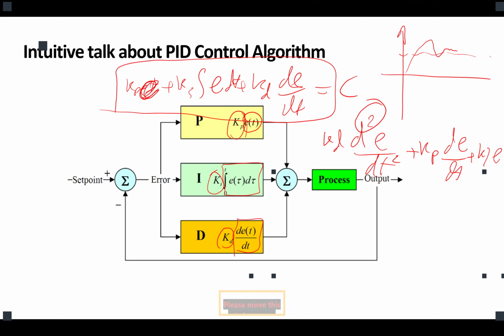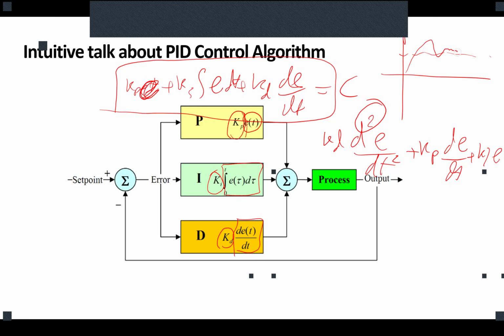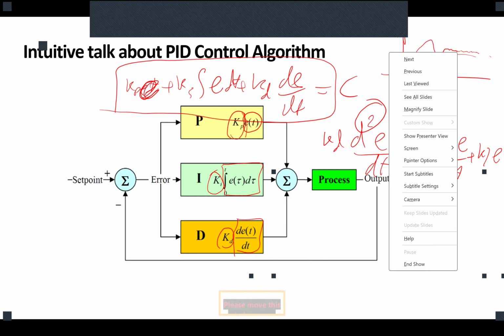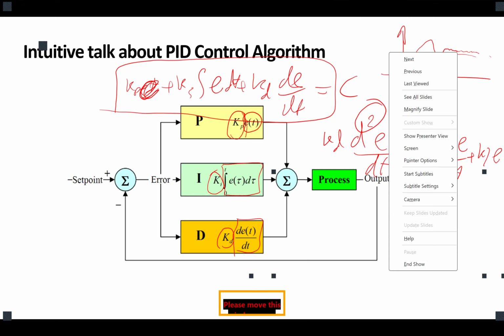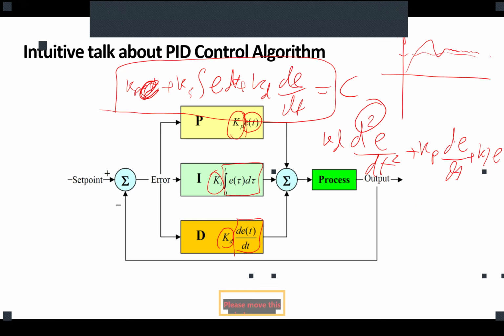So basically it means you can consider that it never gets to the set point, because it's like an exponential decay. It would approach the set point and never reach it, because as much as you get closer, the error never gets to zero, since a proportion of the error is added to the control signal. Are we good? So we are going to have an offset, or you could call it accumulated error, that is always there.